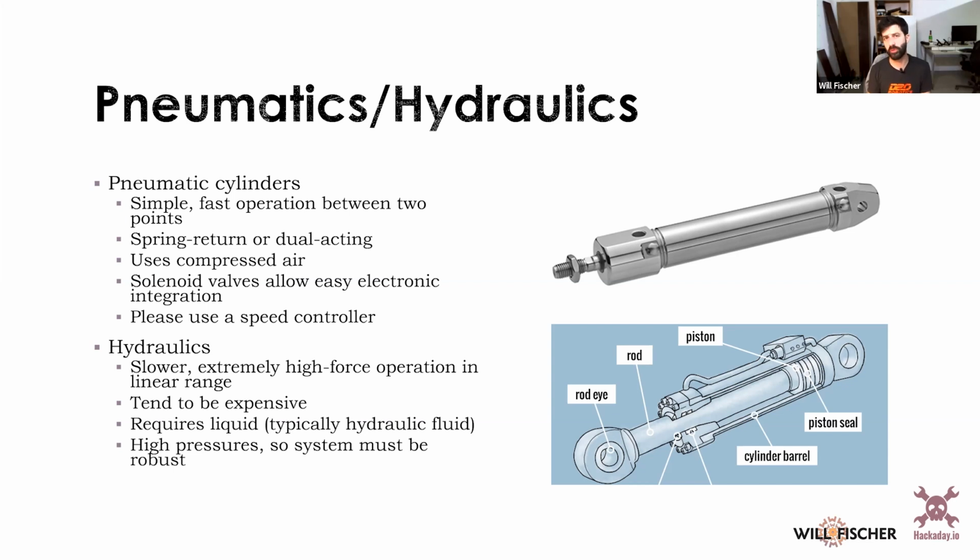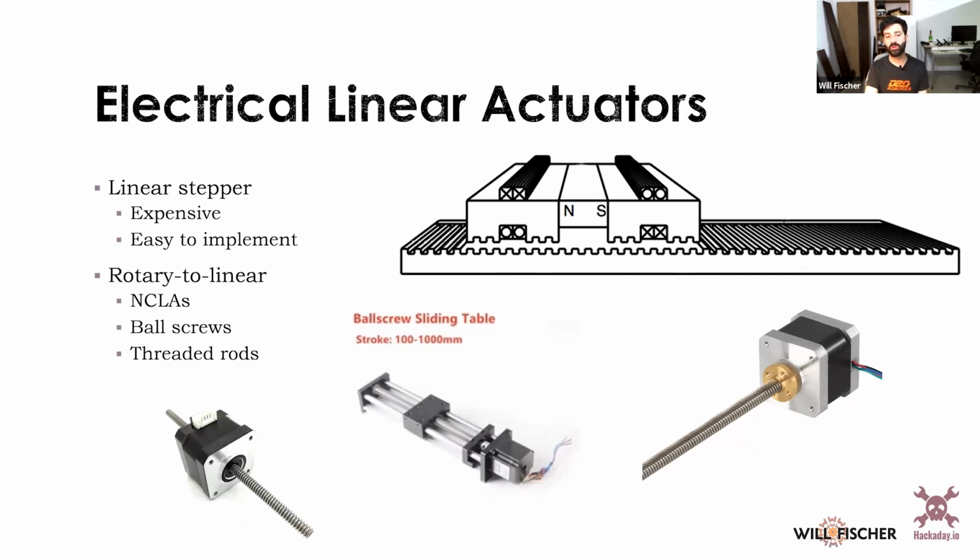And you typically control them using solenoid valves that I talked about last week for easy electrical integration. Hydraulics tend to use very high pressures, so you need to have a very robust system that adds a bunch of weight. The nice thing about pneumatics is that they're very light. You can use electrical linear actuators.